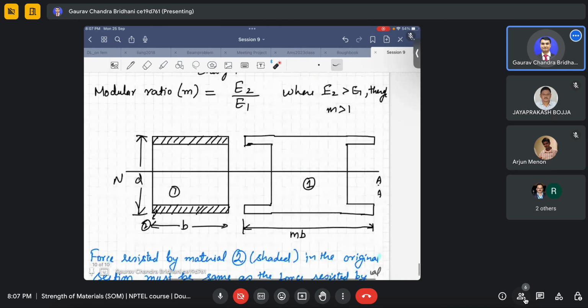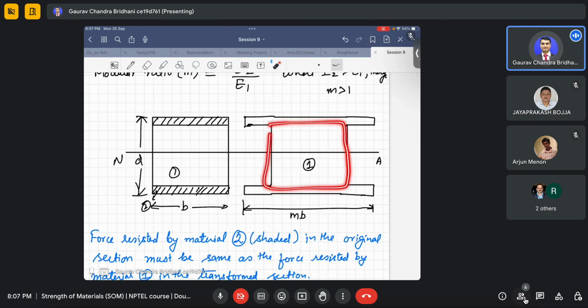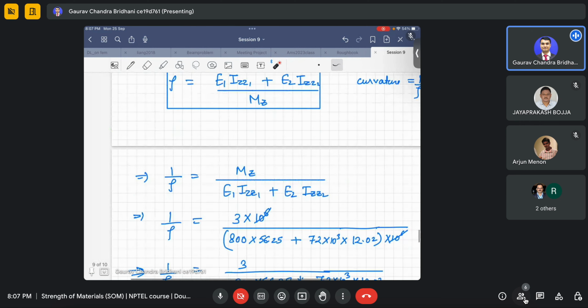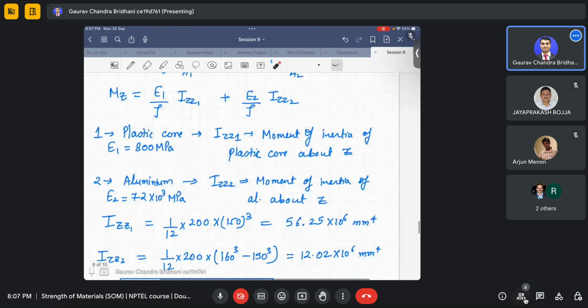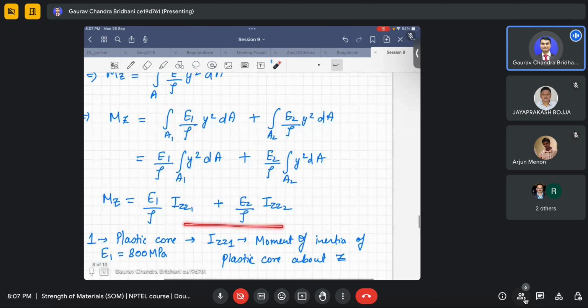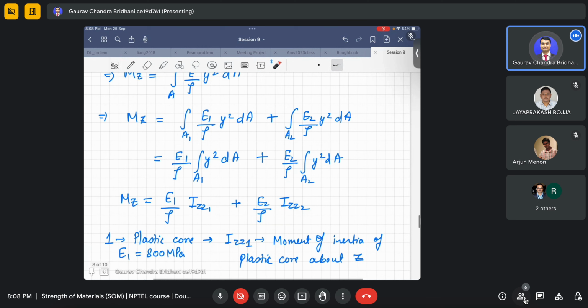But if I talk in two parts, one part being this part and another part being this part, then you can use the above formula itself, this formula which I am saying. If you say, no sir, I just want to use one and I will find IZZ of one thing, then no issue, you just ignore it. Just find IZZ of the whole transformed section, have E as this, define rho as this, that is all. You can find this by putting this IZZ there.